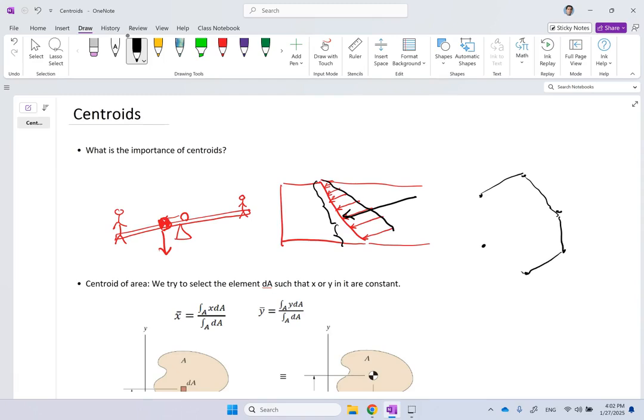And if the center of mass of the robot, if you're looking from top to bottom, it's a top view. If the centroid, center of mass of the robot, is inside this polygon, then the robot is statically stable and it's not going to fall down. Otherwise, it is not going to stay on these legs, and it is going to basically collapse on one end or one direction or the other, right? It's going to tilt to the sides.